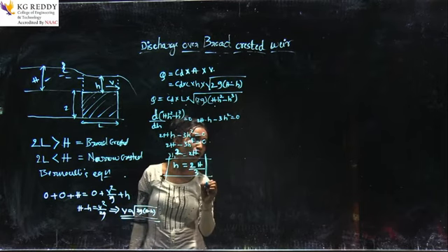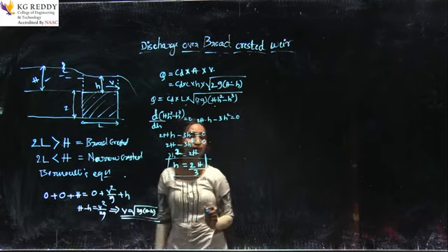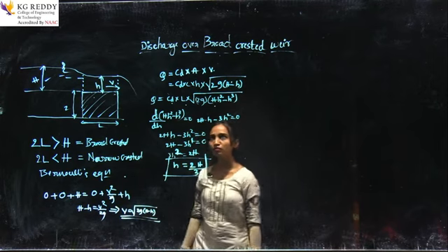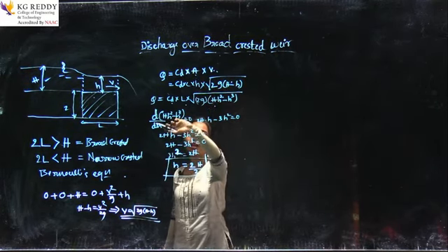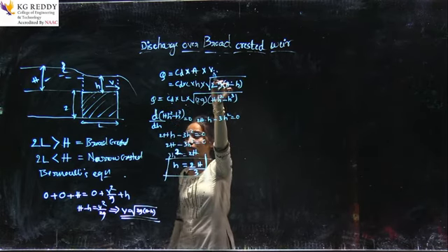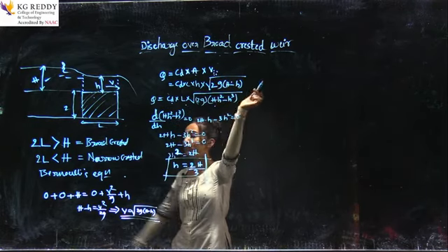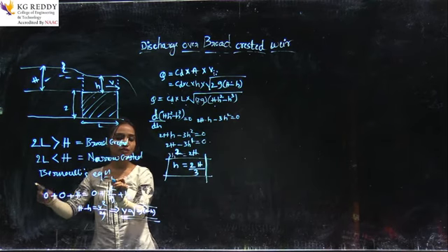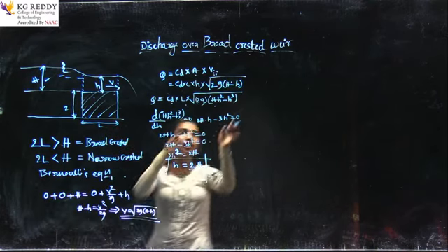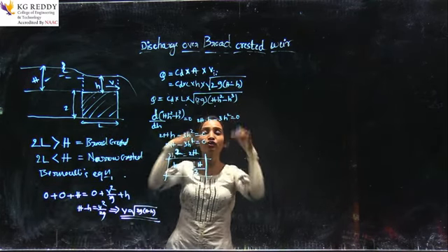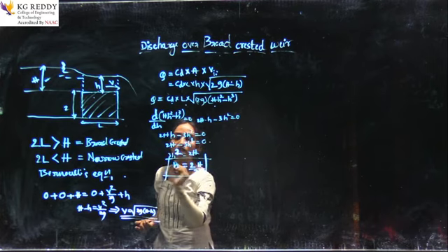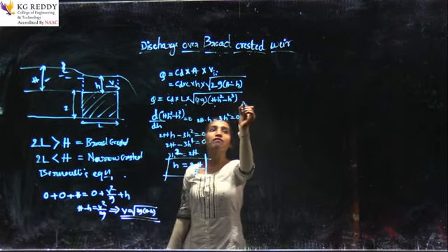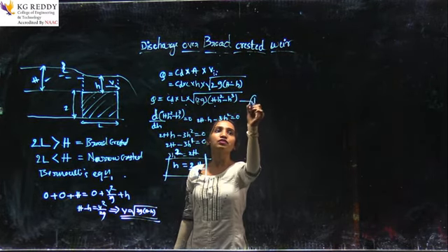See how the length of the derivation is increasing? Please keep it in mind. You should know this. After that, what do you want? Area you want, you know the area. Velocity we want. To find the velocity, you have to go to Bernoulli's equation. Once you get Bernoulli's equation, you substitute, and find where you can get the maximum discharge. So, that term you differentiate, you will get small h. I will keep this equation as equation 1.